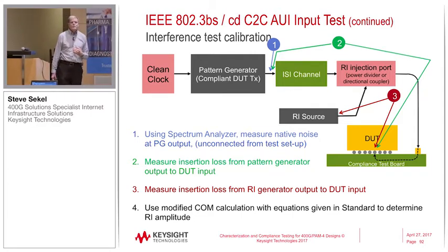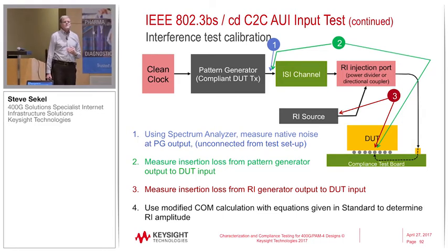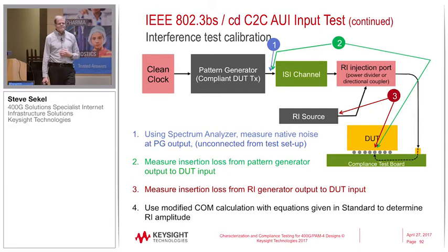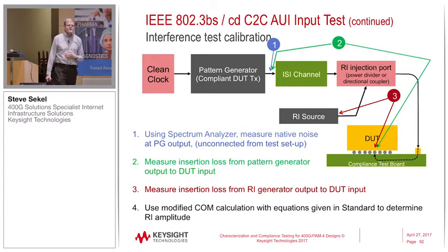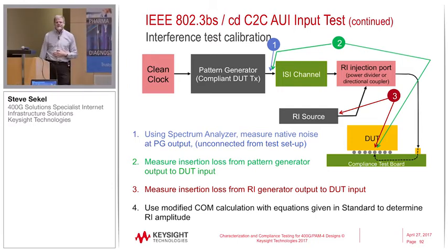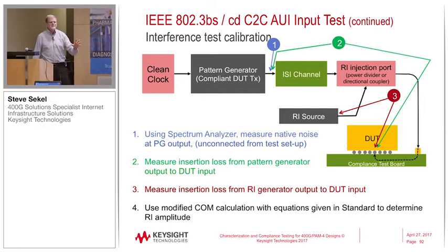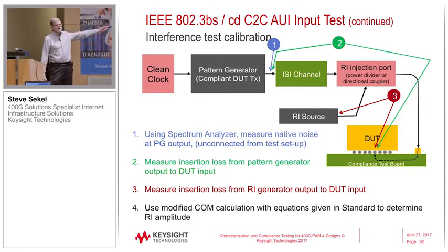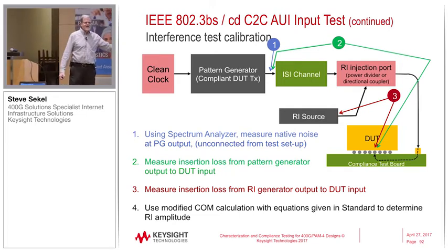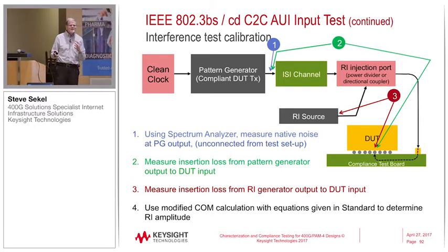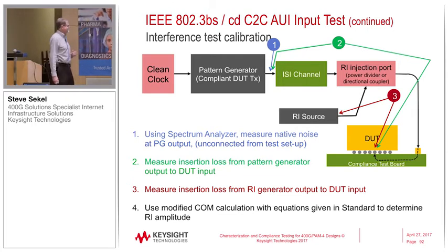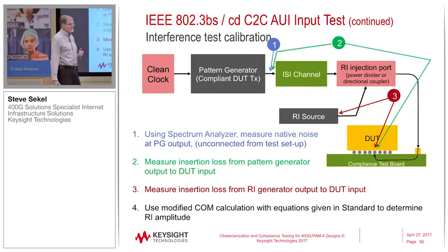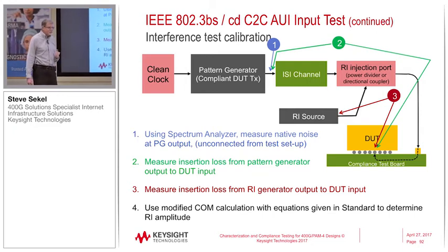So, okay. Again, that RI source had to go all the way up to the baud rate? Has to go up to Nyquist. Yep, has to go up to Nyquist. There's a few companies that make those. I'm working with one of them, they do them all custom, and there are only three bandwidths involved for covering the 10G, all the 100Gs, and the 400Gs. I'm working with an applications engineer to have some part numbers assigned so you can just go order them right off, because right now you have to call them up and they'll make one for you, but I'm trying to get that standardized.